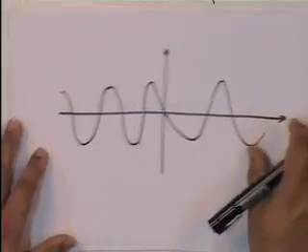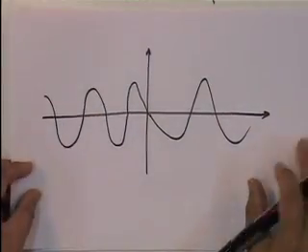Do you understand my point? In that situation, you can define a steady state. The transient will go out, and if this loading has been going on for long enough, we can say that look, we do not care about the transient and we are left with the steady state response. And which is why in harmonic loads, because the load is supposed to be there forever, the initial conditions part of the transient is eliminated. Even if you have slight damping, very small damping in the system, it is eliminated, and what you are left with is the steady state response.